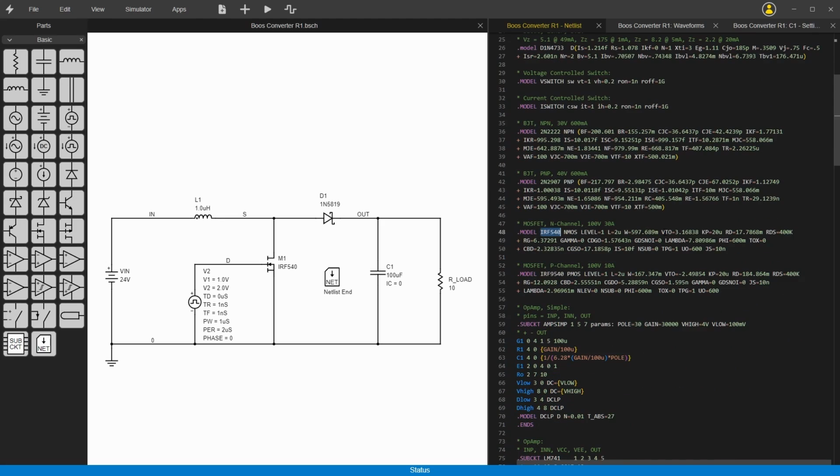And if you look at this VTO, this is the gate threshold voltage required to turn it on. You'll notice that's 3.16 volts, and this is going from 1 volt to 2 volts. So we want to change this to go from 0 volts to something above this. So a good driving voltage might be more like 12 volts for the FET.